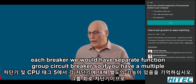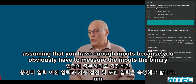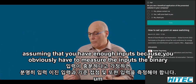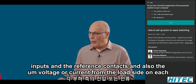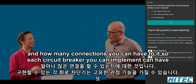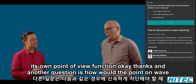So if you have multiple function group circuit breakers in your device, you can apply the point-on-wave in each one of those, assuming that you have enough inputs, because you obviously have to measure the binary inputs and the reference contacts, and also the voltage or current from the load side on each breaker. It's just the size issue, how big you make the device and how many connections you can have to it. So each circuit breaker you can implement can have its own point-on-wave function.